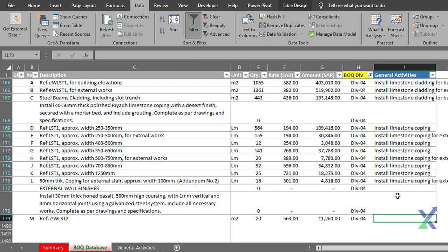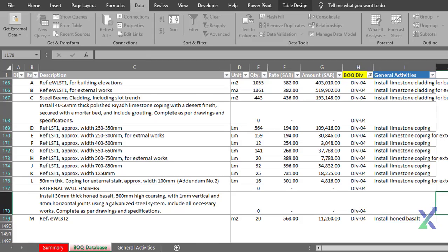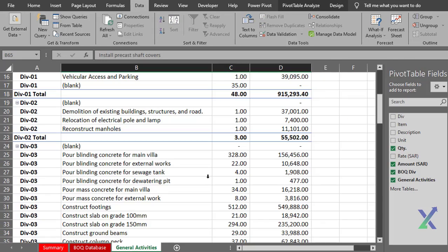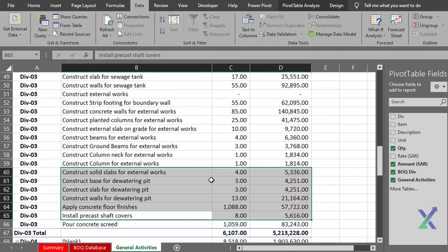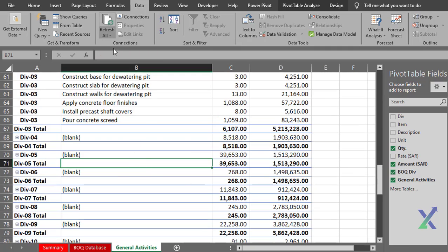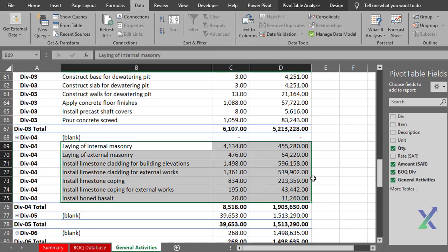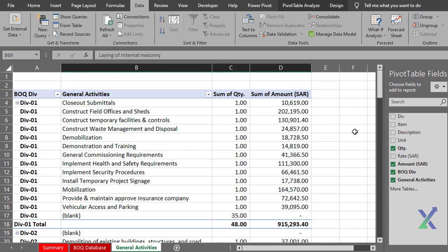In conclusion, we've learned the importance of converting BOQ items into well-defined activities for a clear project schedule. We also discussed methods to maintain activity uniqueness, involve your project team for input, and emphasize the importance of assigning activities to BOQ items with consistent units of measurement.